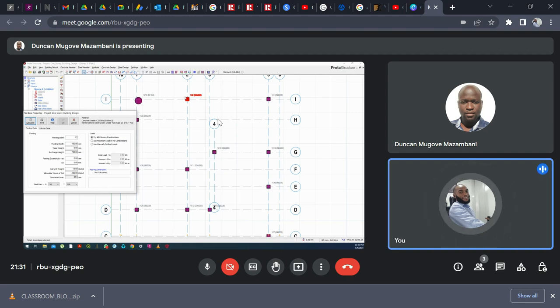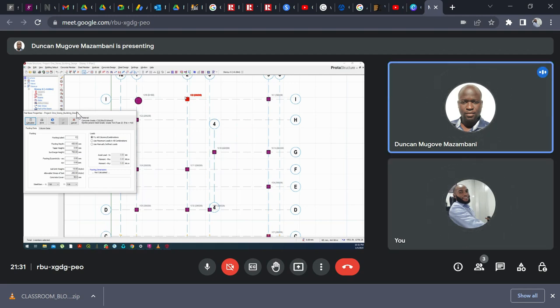But at 8-story to 10-story upward, you should consider using a pile foundation, because when the height of a building or the number of stories increases to more than 10-story, you have to use a pile foundation to be able to carry the load of the structure to a suitable soil and strata. Then when your bearing capacity is between 75 to 100, that's for your bearing capacity.